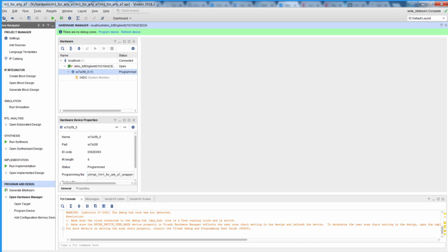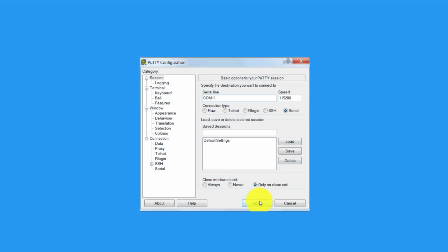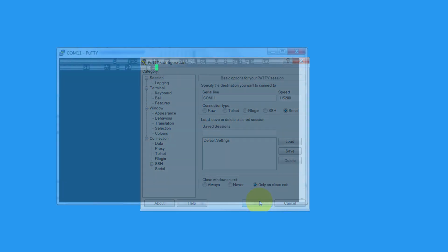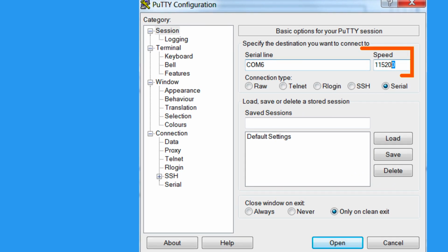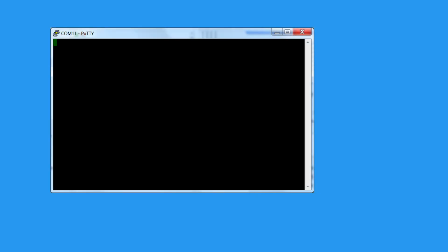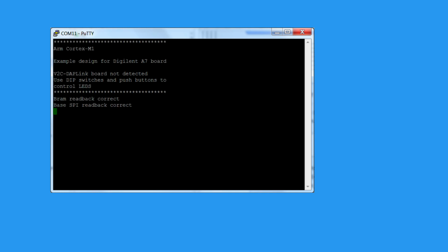Let's restart our terminal with the same settings as before. And because we haven't updated the UART speed in our terminal program, we can see that the banner message is warped. So then if we reconfigure our terminal with the UART speed set to 57,600, which is what the board has now been programmed to use, and if we push the top right hand button on the board to perform a soft reset of the processor, we can now see the message clearly.